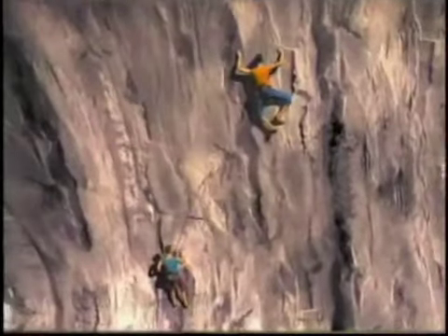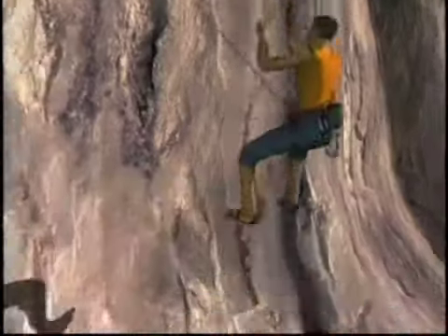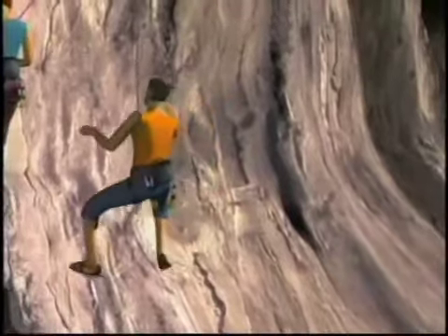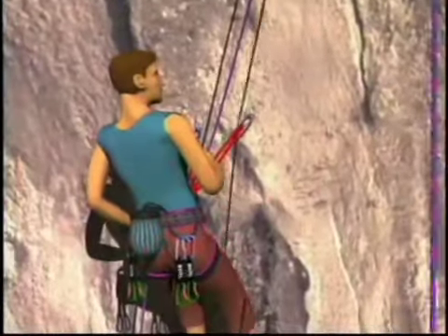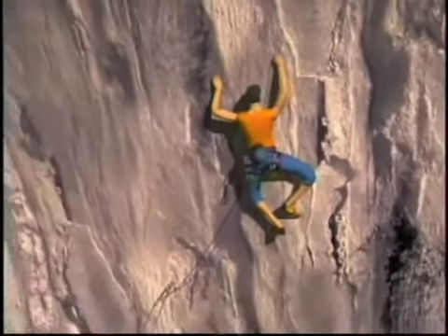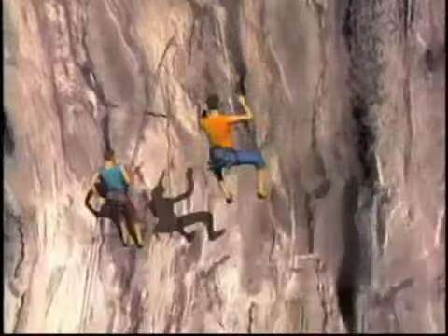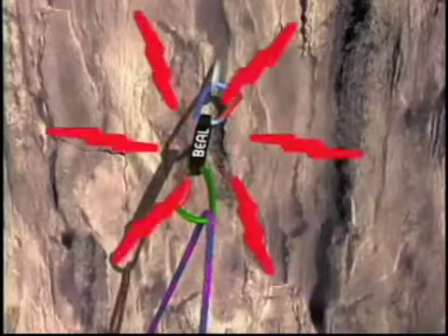The second fundamental concept after the fall factor is the impact force. The impact force is the force transmitted to the climber, to the carabiner, and to the belayer at the moment of arrest of a fall. A severe impact force may have dramatic repercussions for the entire rope chain, on the climber and the belayer, who must withstand the shock, but above all, it is the running belay which may give way.